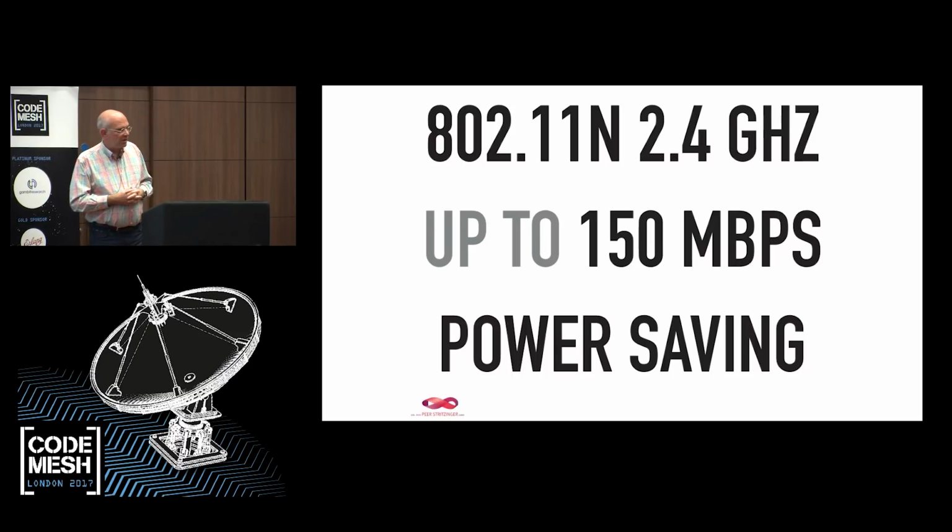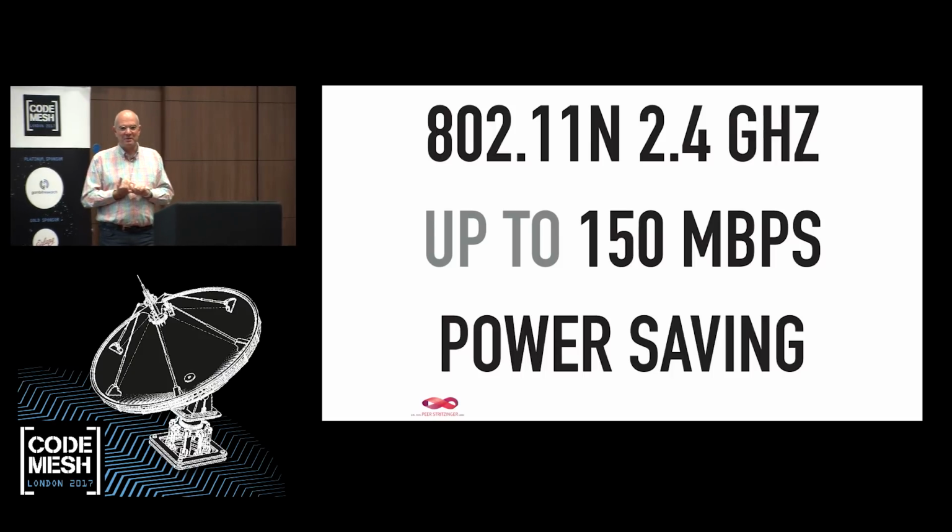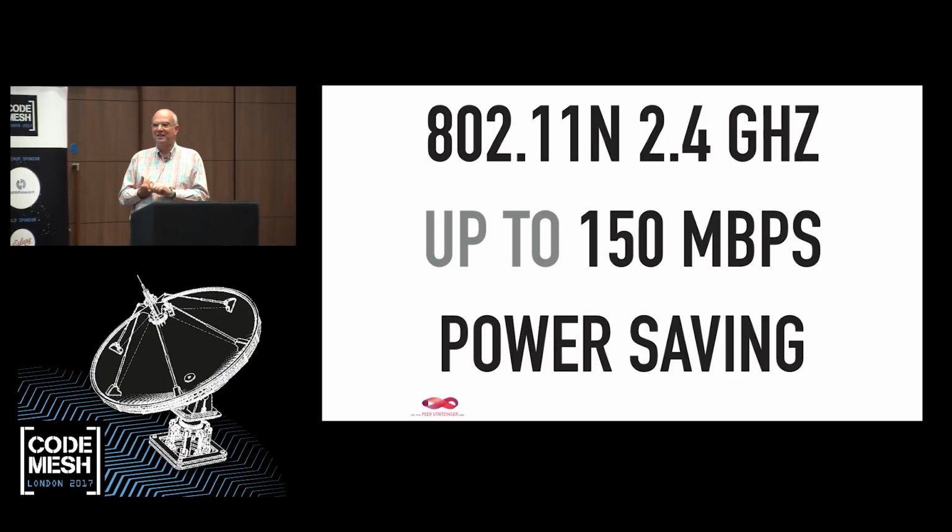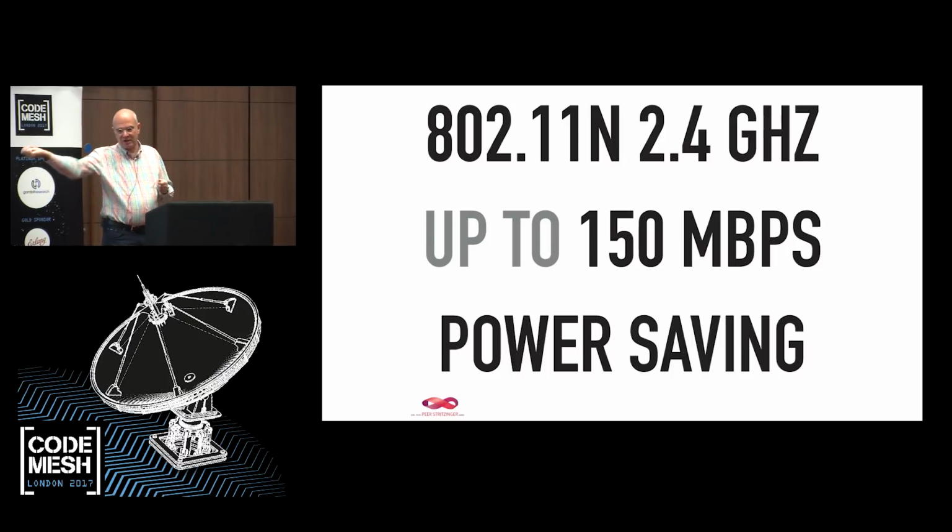You can save power, so it's an embedded CPU, so it has all kinds of power saving modes. You can switch off parts of the CPU. You can also switch off the Wi-Fi chip, because that's the big power drain, which is kind of constant. So you can sleep your CPU all day. If your Wi-Fi is on, that doesn't help at all. So there's basically a switch where you can actually switch off the power of the Wi-Fi.